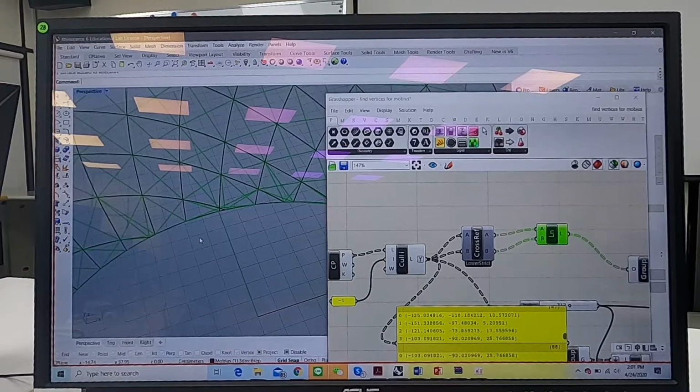So what happens if they don't match? I mean, the built structure and the design model, if they don't match, then the panels you fabricated are useless, right? Because they don't match. So we have to measure all the critical positions of the existing structure and then use that corrected measurement to fabricate.